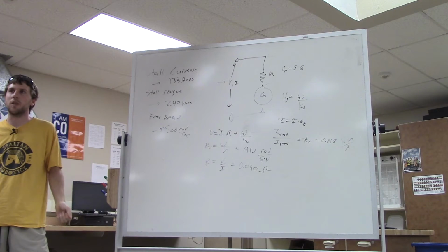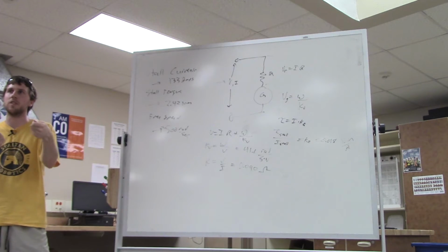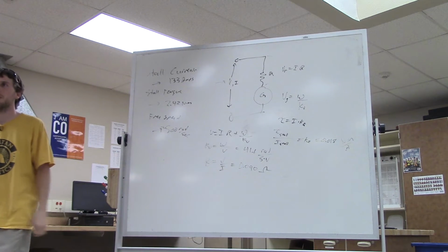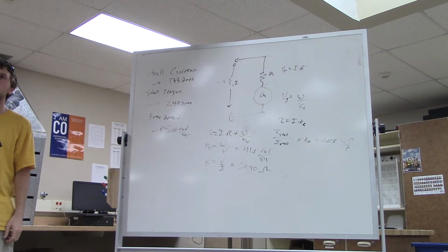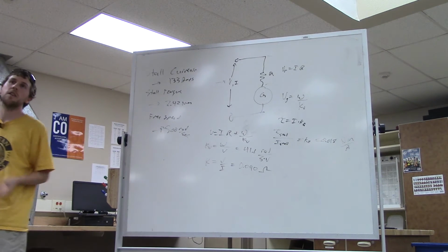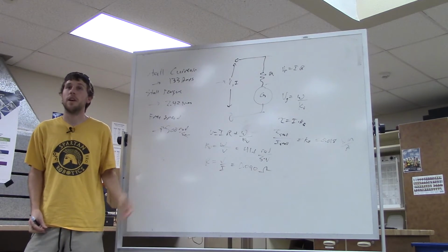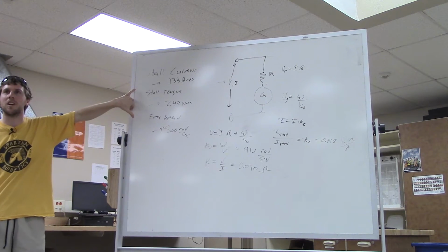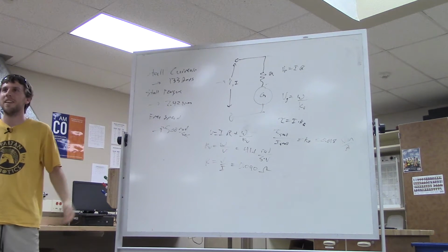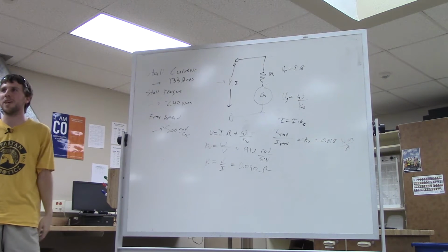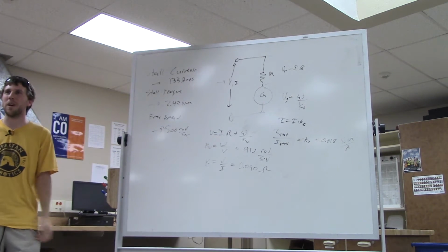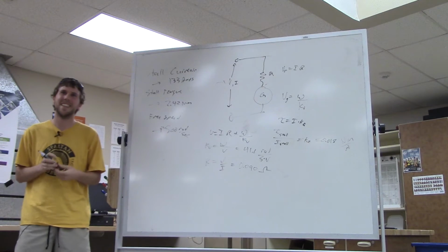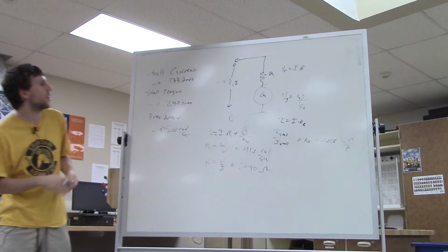We've measured it: when you stall it against a wall, measured at the motor, we'll see 6 volts. The same equations then apply, you just don't have as much current to work with. But we're not stuffing 133 amps through the motor, right? That's because you have resistance in the rest of your system. But someone, and actually that someone is here, put these on a dyno and figured out all these numbers, and they put 12 volts in and got 133 amps. That's not with a battery, that's with a power supply. You can run 500 amps through that circuit breaker on the robot, just not for very long. Yeah. Okay.